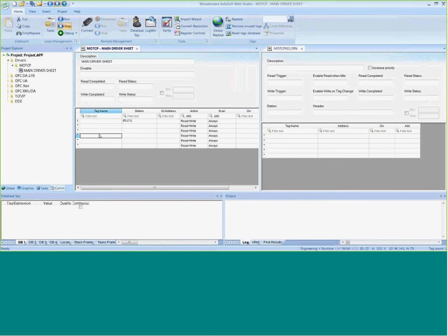So we moved that array of 1,000 characters, 1,000 part numbers, into its own separate standard driver sheet and just triggered that when it got a database update from the plant server. So they had that huge amount of data being transferred every cycle, and then the cycle time went down to like 30 milliseconds. So it ended up being a really clean way to do that.